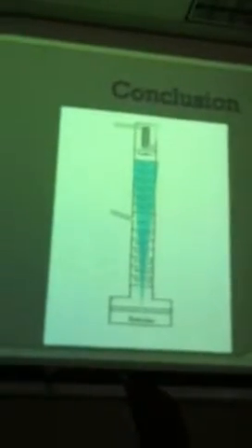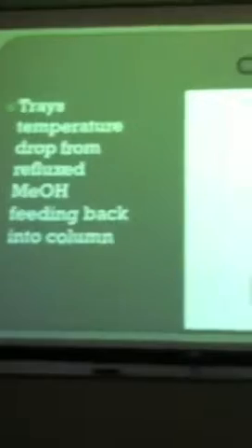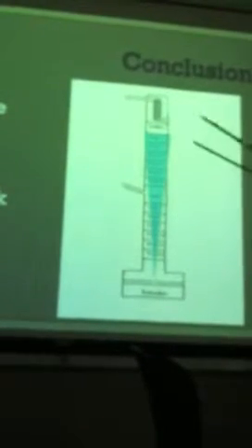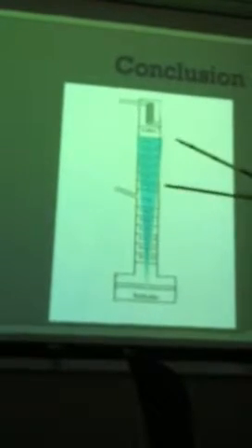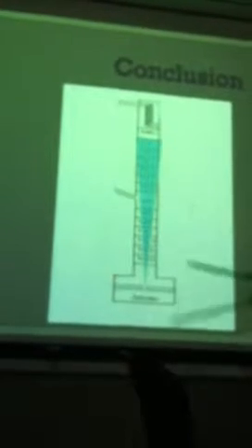So why do these drop? It's because with 100% reflux, that methanol is coming right back down into the trays. So as wattages are decreased, more and more methanol will fall down, and that's why this temperature is so much higher than tray 1's temperature.